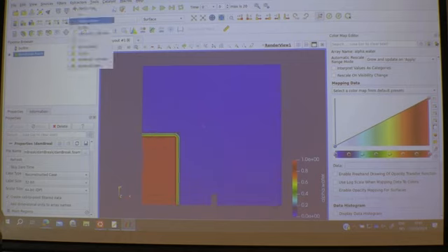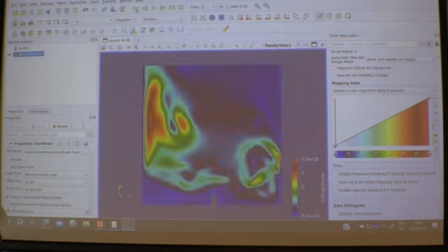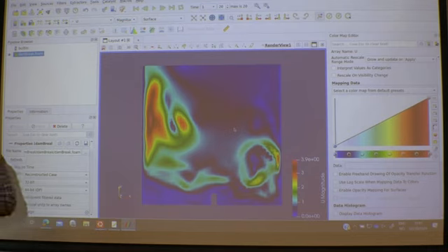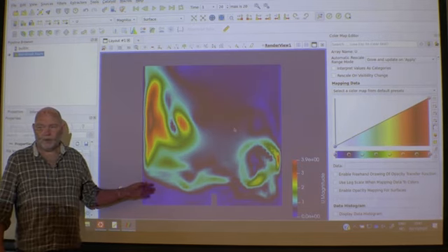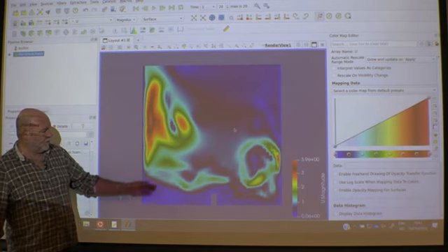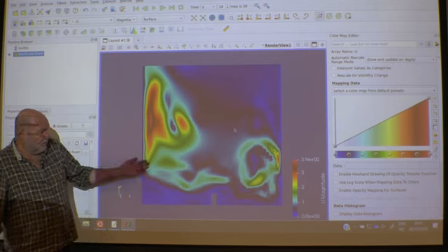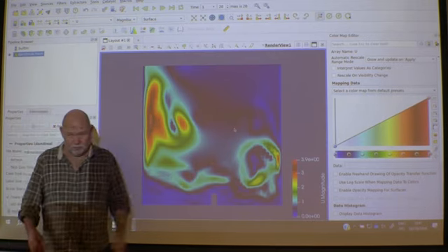So now I want to have a look at the velocities. So we start with 0, and then we run. Well, that was a little bit rough, wasn't it? Let's rescale him and run again. Looks rather violent, to say the very least. Why? Remember, he's solving the Navier-Stokes for both phases, both for liquid and for air. And yeah, you can have velocities here. You don't even see where is the boundary between the air and the water. You can't really see it. So typically, this will be velocity in air, and this will be velocity in water.